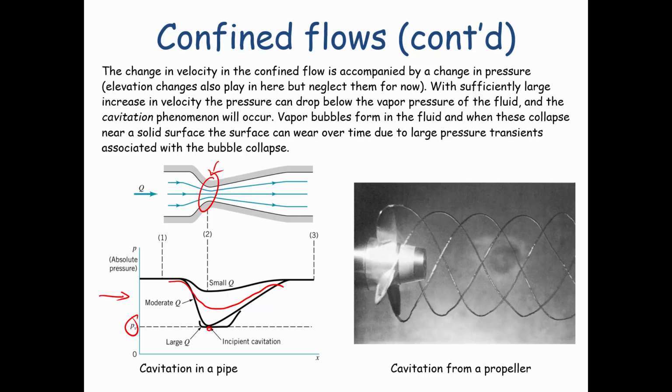When it reaches that point, you can then have cavitation if it goes below this point. So if the opening in the pipe gets small enough, velocity gets high enough, the pressure will decrease to the point where you can have cavitation. Now, for water, that occurs if the water pressure drops to about 8/10 of an atmosphere negative, and then